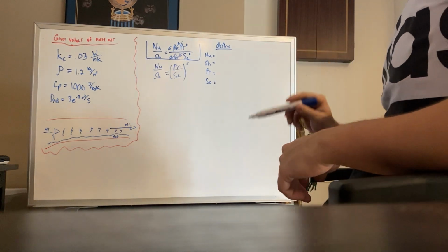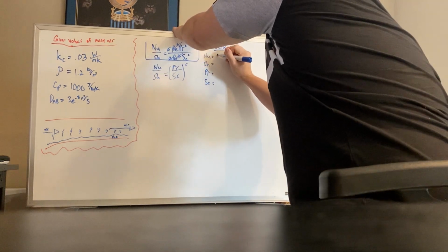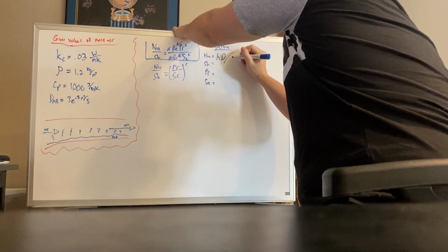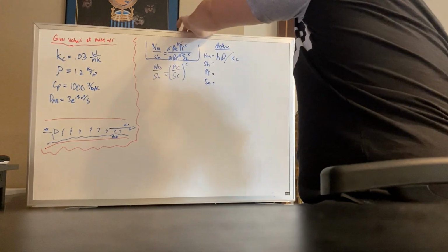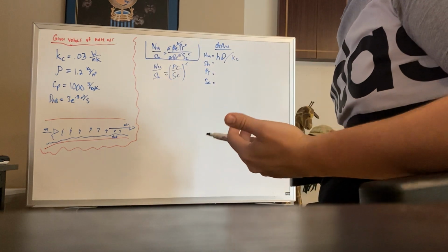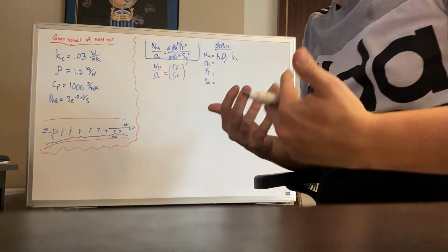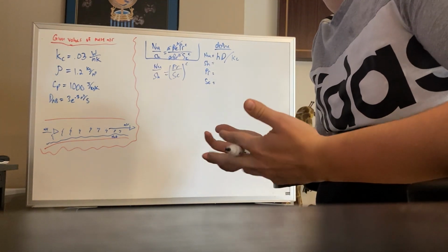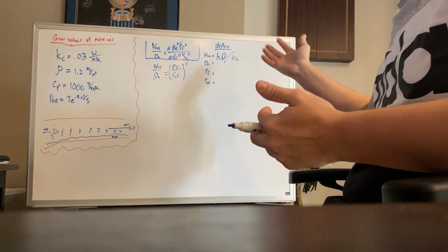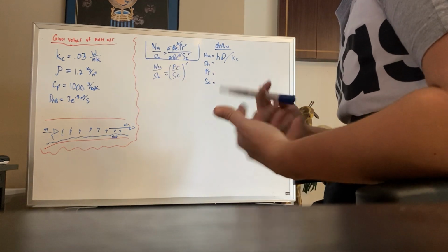Starting with the Nusselt number, you can redefine this as the heat transfer coefficient multiplied by the diameter, all divided by the thermal conductivity, k. And this is really what we're going to try to work toward, to isolate the heat transfer coefficient over the mass transfer coefficient, so we can see pretty much how much heat is transferred per some sort of mass. Really, we could say it's a kilogram, we could say it's a gram, but it's dependent on whatever we have.